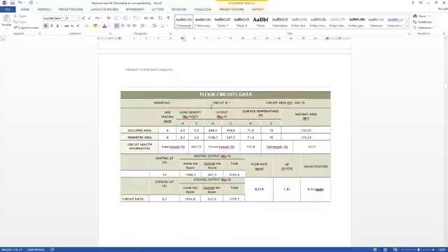We have our manifold, which is circuit number 1, with our circuit area is 300.76 square feet. In the occupied area, we have our pipe spacing, which is 6 inches, and our perimeter area, which is 6 inches as well. For our load density in BTUs per hour per square foot, we have it broken down into our heating and cooling, as well as our output and service temperature for heating and cooling. We also have our radiant area in square feet for our occupied and perimeter area.